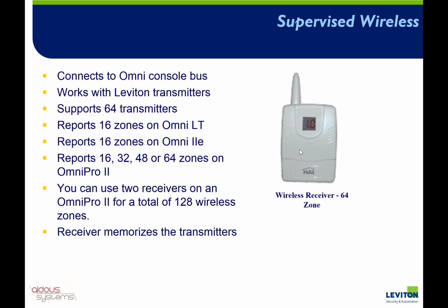It does use 400 megahertz, which is a low frequency signal, compared to Wi-Fi, which is 2.4 gigahertz. It doesn't go through walls very well, quite lossy. This is 0.4 gigahertz, so it's very low frequency in comparison, and will go through walls and is much less lossy than the wireless we're used to with Wi-Fi.